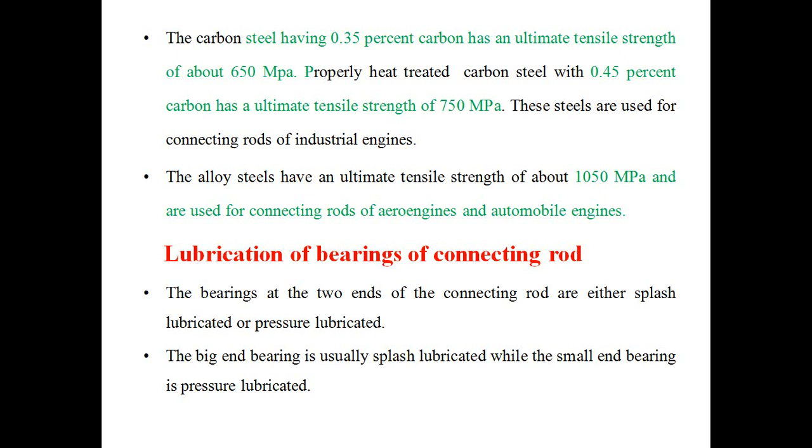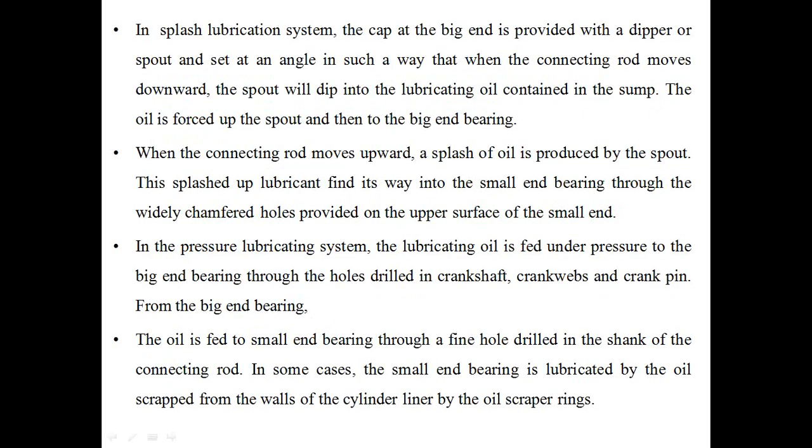The next topic I will discuss is the lubrication of the bearing of the connecting rod. The bearings at the two ends of the connecting rod are either splash lubricated or pressure lubricated. I have already shown the provision of how the splash lubrication is done in the bearing. The big end bearing is usually splash lubricated, while the small end bearing is pressure lubricated.